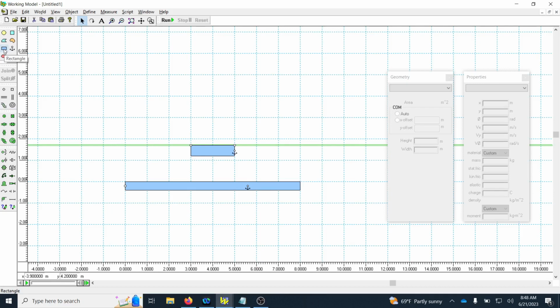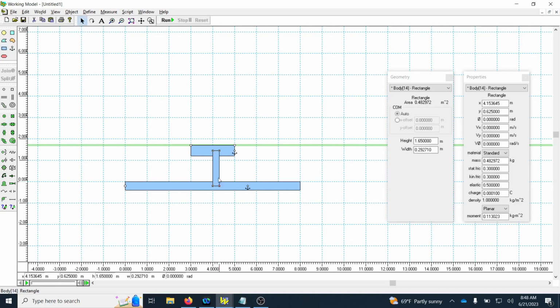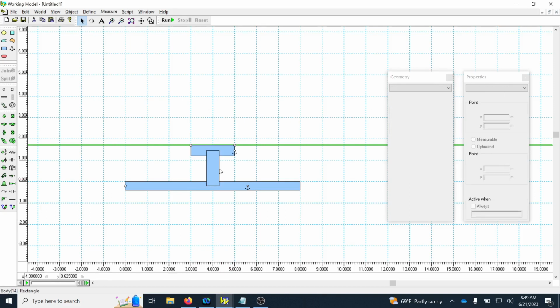So the other thing I have to do is to create a coupler between the slider and the door. So let's create a slider starting from there. That's fine. And then I'm gonna pin this end and then change its width by twice as much. So I'm just gonna say times 2. So it goes that way. And then I'm gonna pin this end of it.